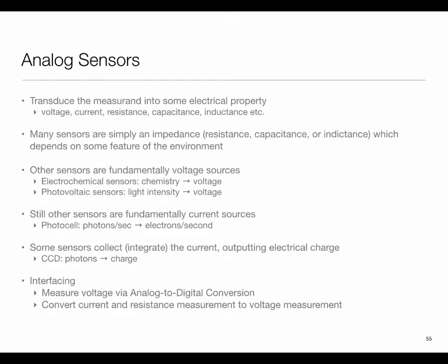Simple sensors are analog sensors. So if you look at your embed, it has an accelerometer, it has a touch sensor where you slide your finger. So the touch sensor where you're sliding your finger, what happens when I touch it? Capacitance changes because our body has a capacitance to the ground, and then it is feeding into an A to D converter, an analog to digital converter, and that change in capacitance translates into a change in voltage, which is what is being read, and you see it translated into a position.